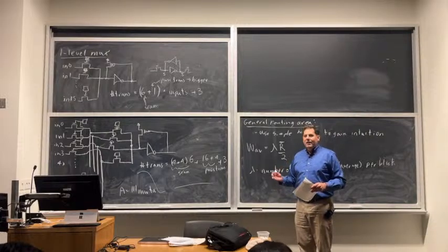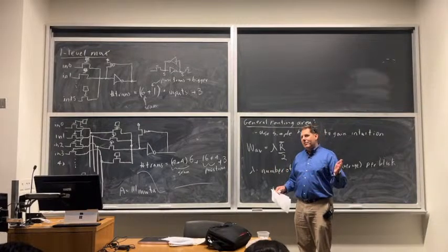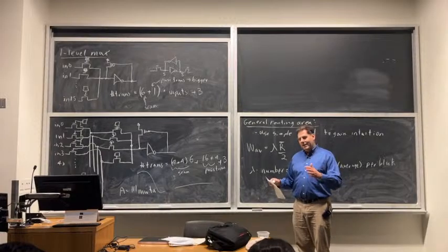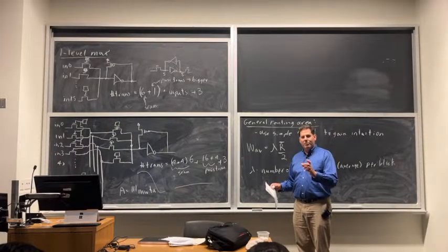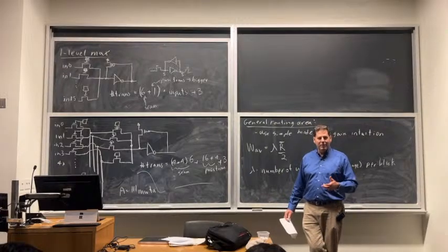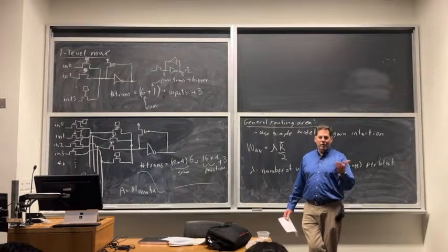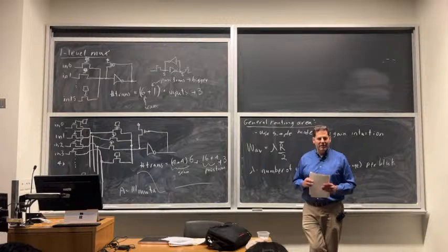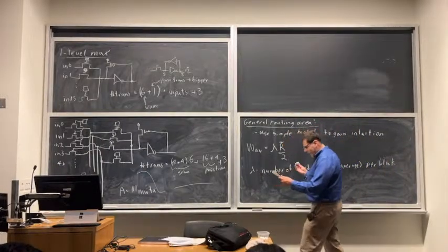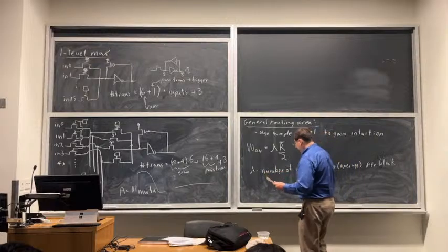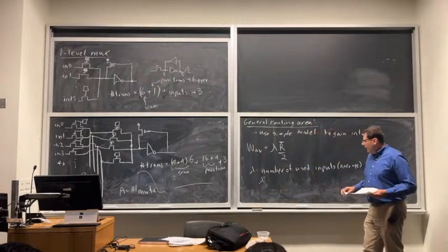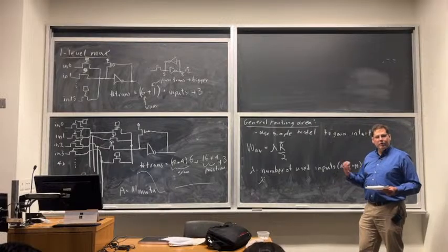Why is it a little bit less? Maybe I've got a bunch of flip-flops before some AND gates. And the tool, when it goes to figure out how to put this in 4-LUTs, just can't find 4 inputs worth of work between these flip-flops. I only found 3 inputs worth of work. So this lookup table is only going to use 3 of its inputs. Does that make sense? It depends on the exact structure of your circuit and how good your synthesis tool is.